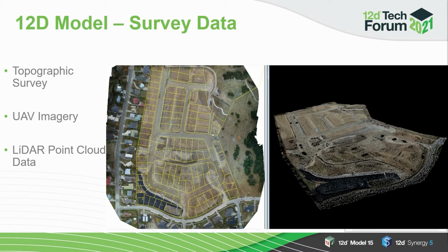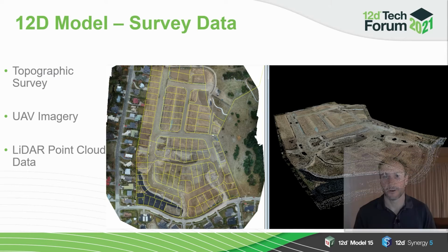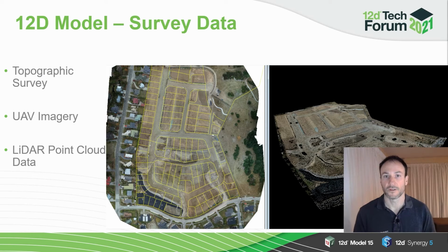We're getting LiDAR data from the local authority, so we're using 12D to bring that LiDAR data in, create surfaces from that, and super tins from that. So 12D can handle all of this data really quite easily, and the 3D viewers in it are right up to scratch with other types of software.